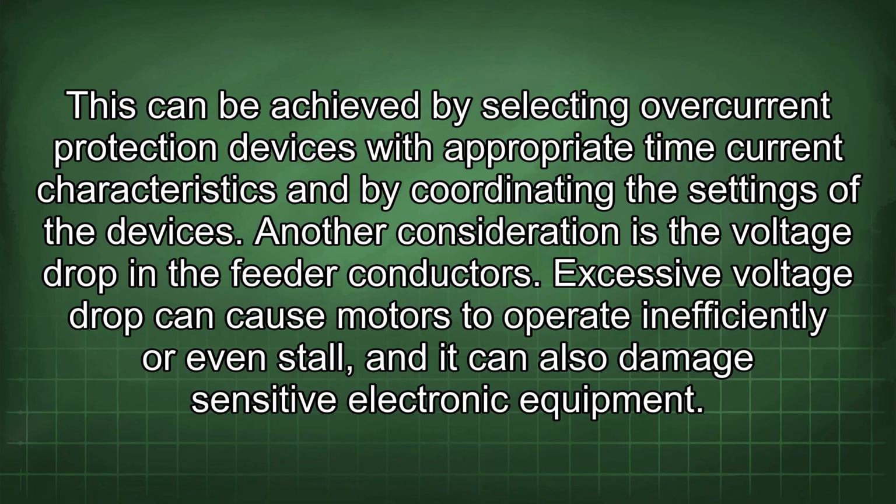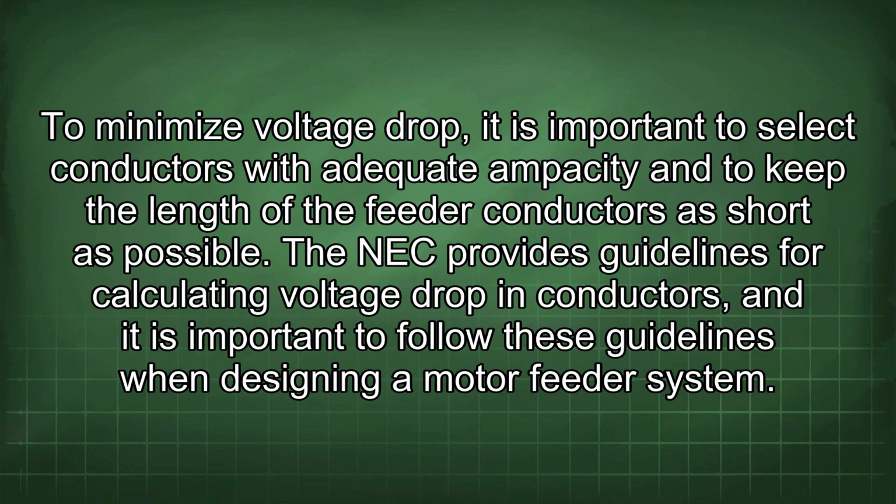of the devices. Another consideration is the voltage drop in the feeder conductors. Excessive voltage drop can cause motors to operate inefficiently or even stall, and it can also damage sensitive electronic equipment. To minimize voltage drop, it is important to select conductors with adequate ampacity and to keep the length of the feeder conductors as short as possible. The NEC provides guidelines for calculating voltage drop in conductors, and it is important to follow these guidelines when designing